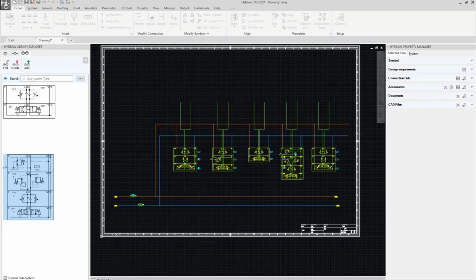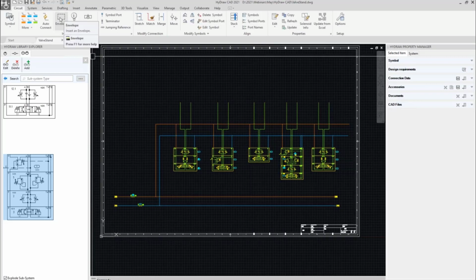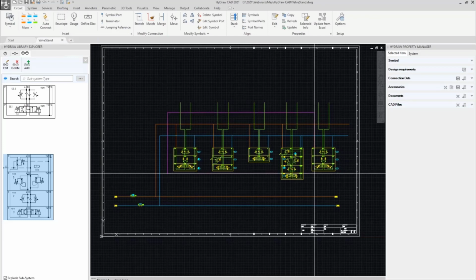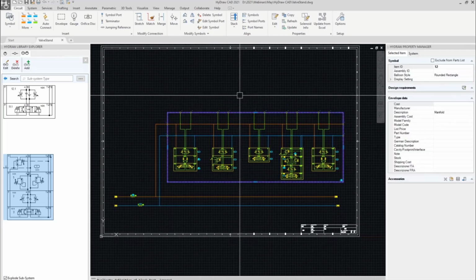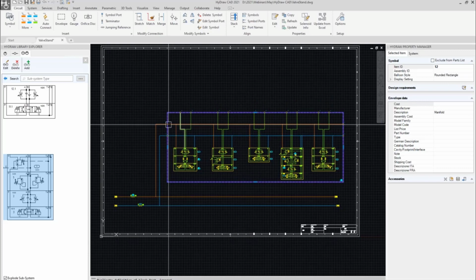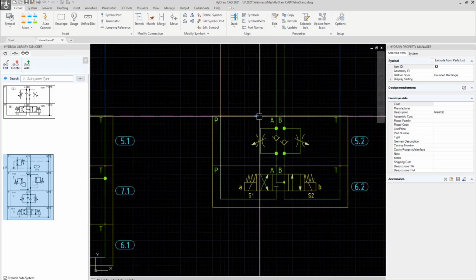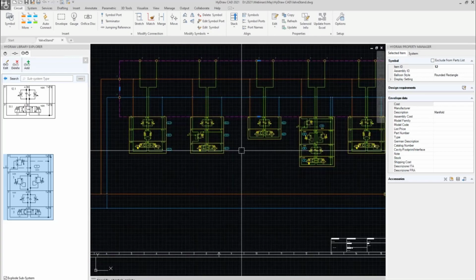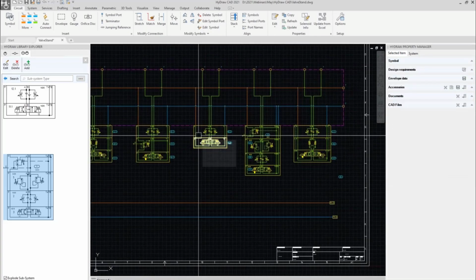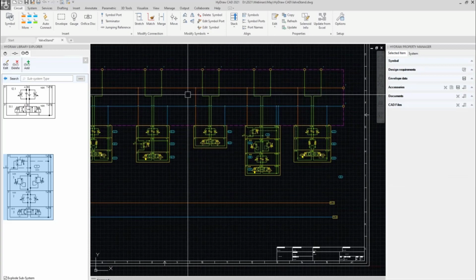And let me start making the envelope. So the command is called envelope, and we create an envelope that is crossing connection lines. Usually when I have sandwich mounted valves, I make the envelope outside. Then if you want, you can really put it directly here so the representation is good, but that is really how you want to describe the valve stand.